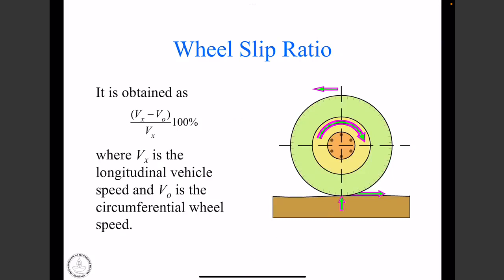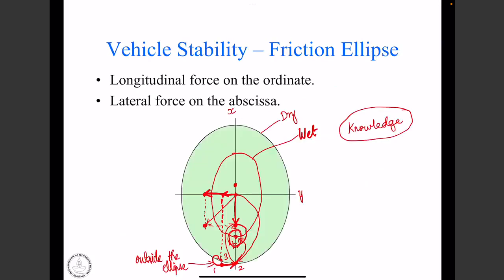In this friction ellipse, sir, why is lateral not as big as the longitudinal? Why is it not a friction circle? It depends on some tire design, right? That's why some people will call it a friction circle. I have drawn it in general as a friction ellipse. In some tire designs, it may be in the form of an ellipse, but very close to a circle. Yes, it depends on the tire construction.